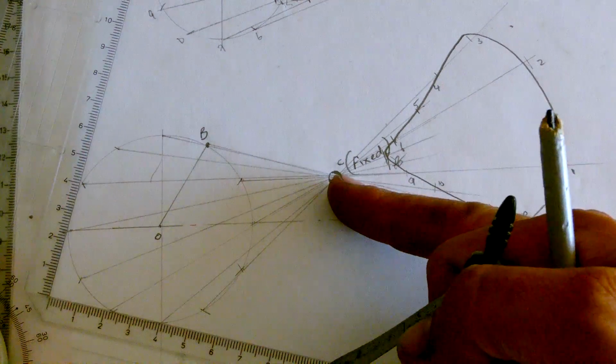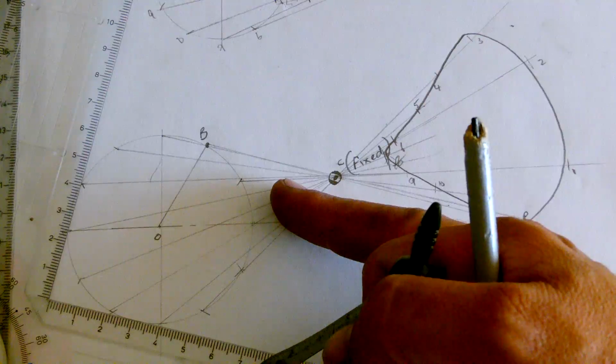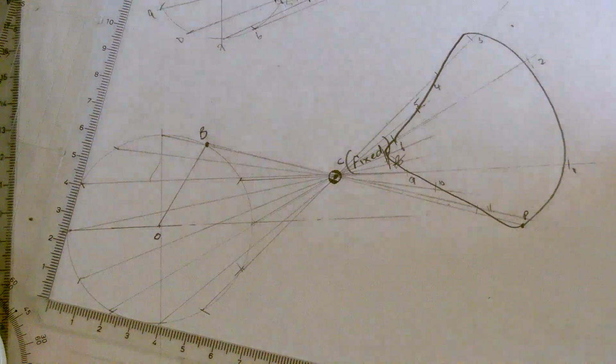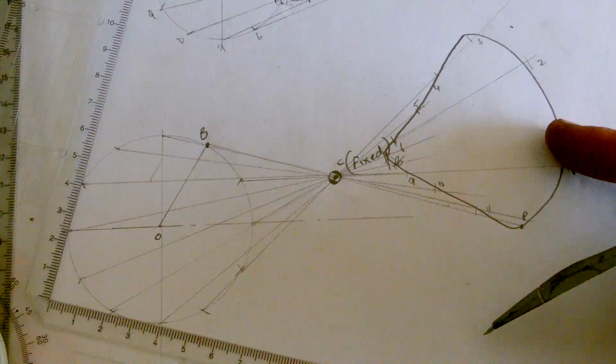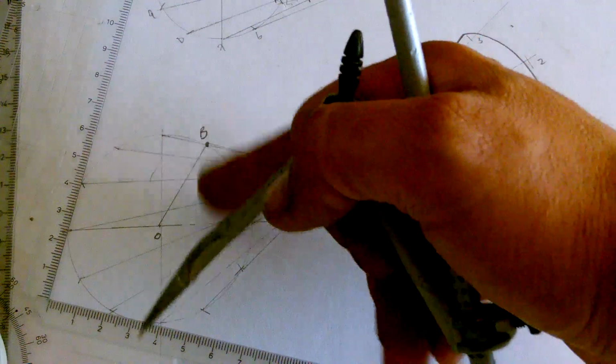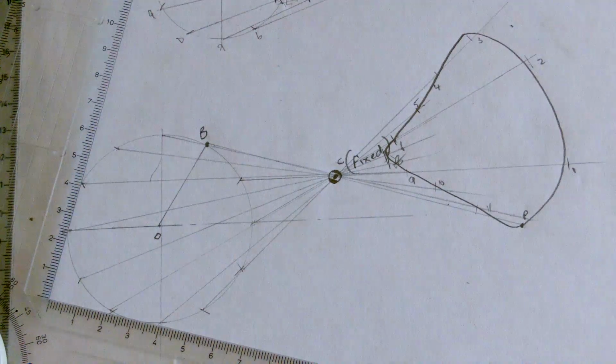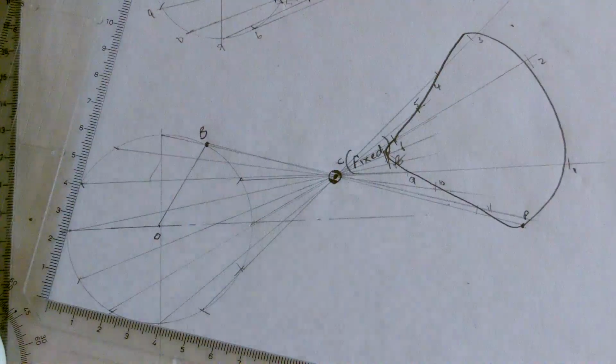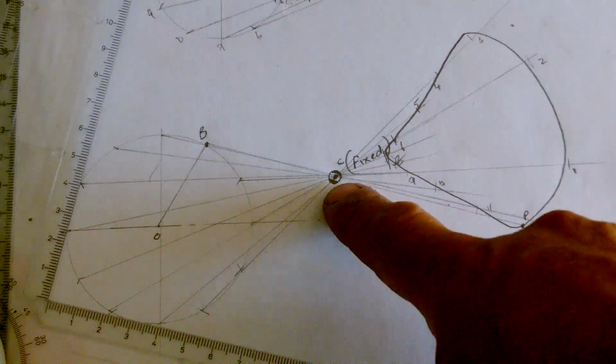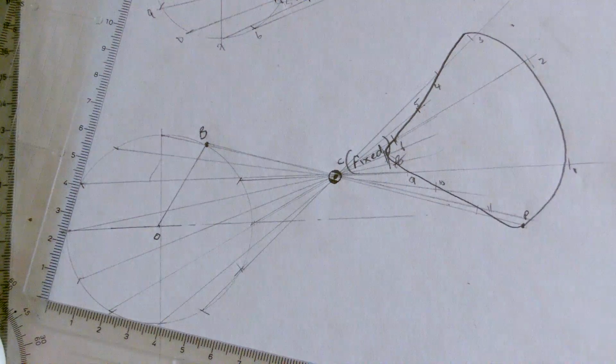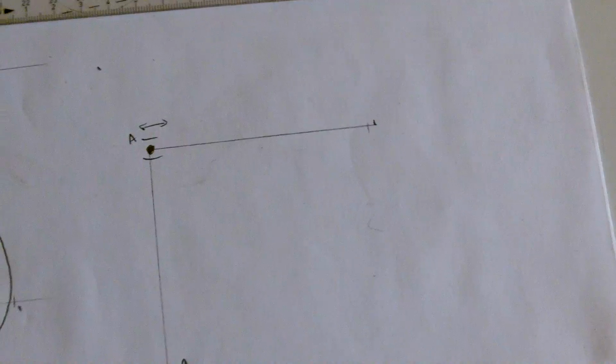Now with that swivel bearing moved closer to the crank, you get a bigger locus here, because the throw would be greater. So that's the difference between the slider we did before and the swivel bearing or rotating bearing which we did now. Let's see another example.